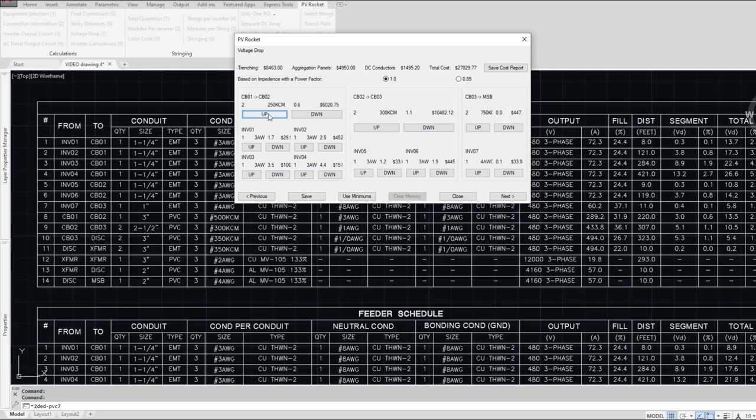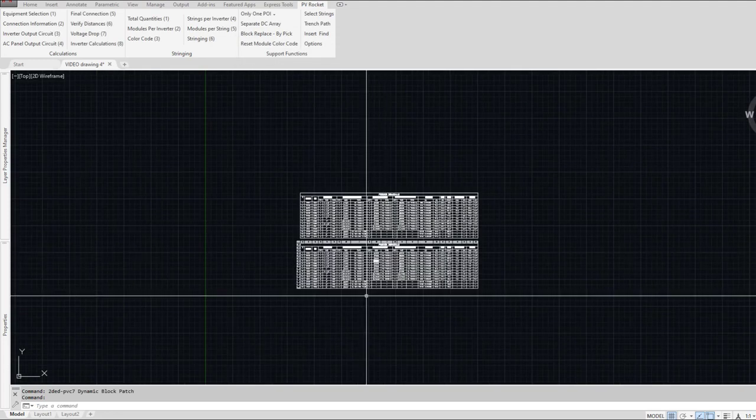So what does the up mean? Up is the ampacity increase. So we went from one run of 750 up to, which 750 is good for 475. Divided by 2, that's 237.5 amps. The next size up is 250 kcm, and that's what we got. So I drew out a little chart here for you. Let me hit close on that.